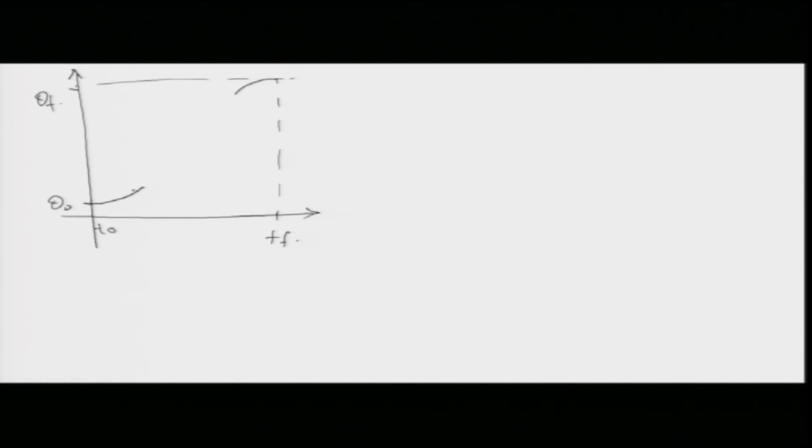Now, let us draw it here and see how we can derive the equations. So, let me draw it here. This is my x axis and y axis. Some things to note here. This is the starting point theta naught, it starts at theta naught and ends in theta f in some time T f. So, this is my start point T naught, this is my end point T f. It is going to start slowly like this, and at T f it is going to end slowly like that, and in between it is going to become linear. So, this part is linear.